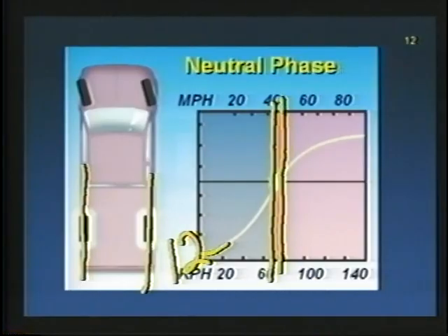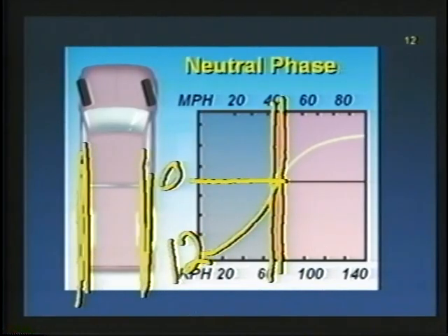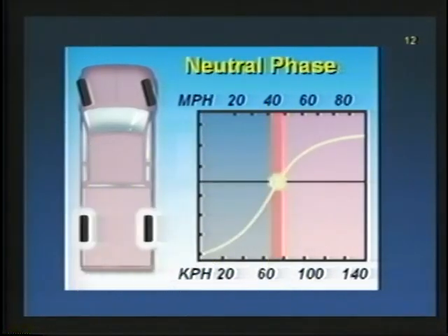Slowly, we're picking up speed. We're getting rid of that, getting closer to this point right here. That's 0. That's the rear wheels in that straight ahead position. Not turning at all. We're also using neutral phase anytime the system detects a problem. So if we see a problem with the system, no matter what's going on, the speed we're dealing with, it's going to go ahead with the rear wheels in the straight ahead position. So kind of a default position as well.